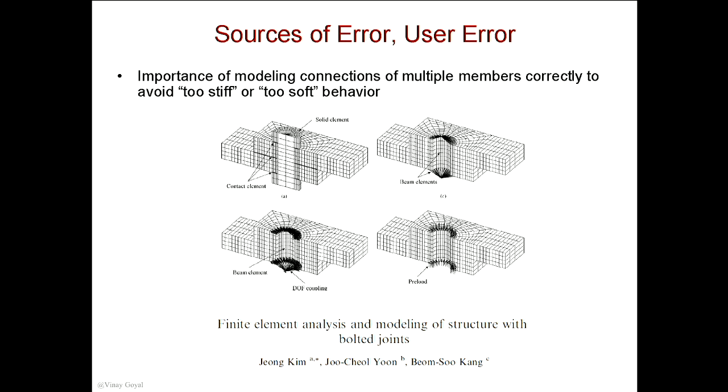Another approach is to convert the solid elements, these plates, abutments, into shell elements. If they're long enough, so they're thin in this direction, but long in the other directions, then in that case, you can represent this as shells, and then use a beam to connect the two shells together using a distributed coupling on the shell, and then beam elements represented in the bolt.